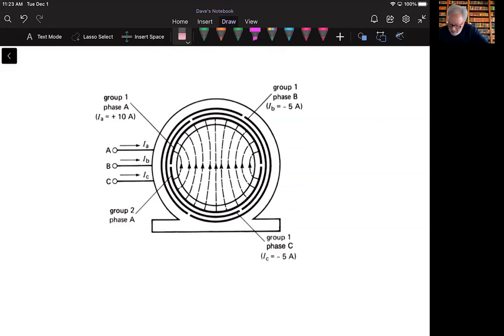But what we do now is we've got this coverage through the entire interior of this stator, right? There's none of those gaps where the flux density is lacking. So you get a machine that's much more efficient that way. You're not losing or have those areas where the flux is less at any point.